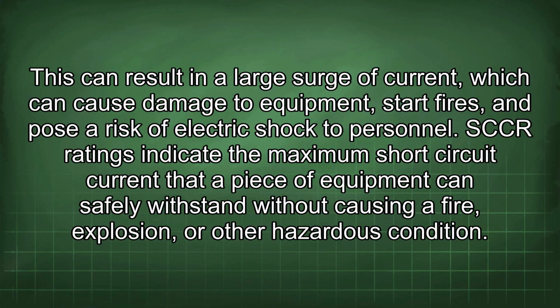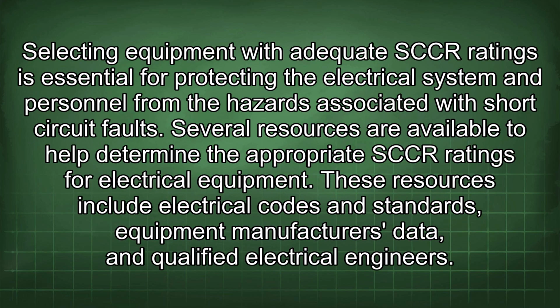SCCR ratings indicate the maximum short-circuit current that a piece of equipment can safely withstand without causing a fire, explosion, or other hazardous condition. Selecting equipment with adequate SCCR ratings is essential for protecting the electrical system and personnel from the hazards associated with short-circuit faults.